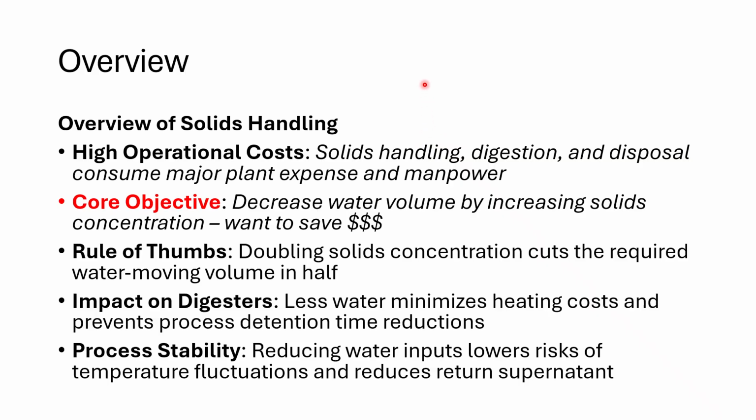Yes, it incurs costs, but it's relatively easy to move that liquid or that high water content solution around. With solids, we're dealing with more like a thickened sludge, like flowing mud, if you will, almost. And that solids handling, we can handle it with thickeners or a digester, and we are eventually going to want to dispose of that sludge.